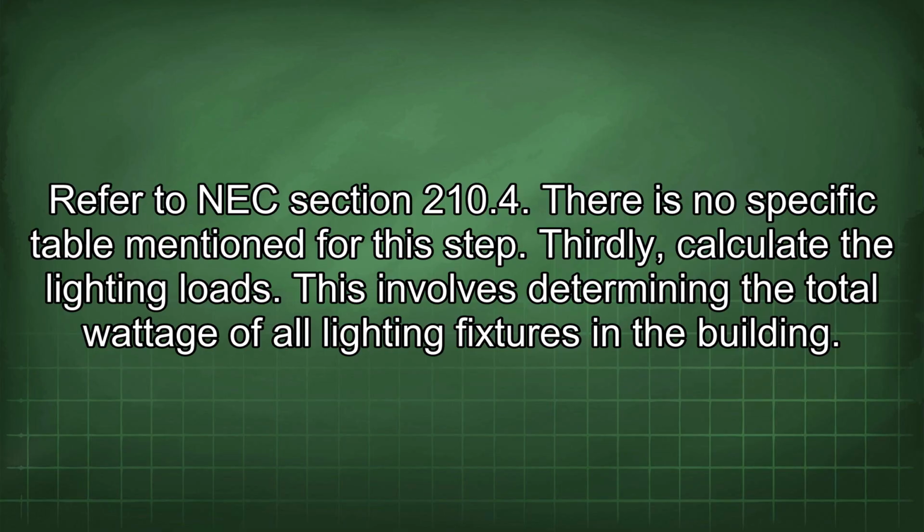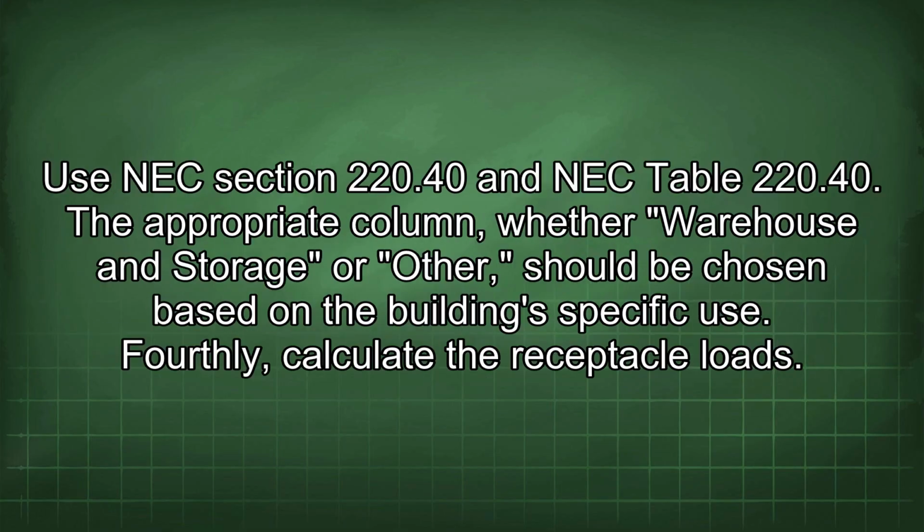Thirdly, calculate the lighting loads. This involves determining the total wattage of all lighting fixtures in the building. Use NEC Section 220.40 and NEC Table 220.40. The appropriate column, whether warehouse and storage or other, should be chosen based on the building's specific use.